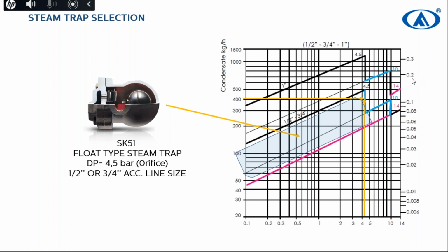Thank you. Very heavy condensation condition. What is the solution to remove heavy condensation from a heat exchanger? The solution has 2 ways. If I understand your question correctly, you can use condensate transfer pumps. It can discharge up to 16 tons per hour.